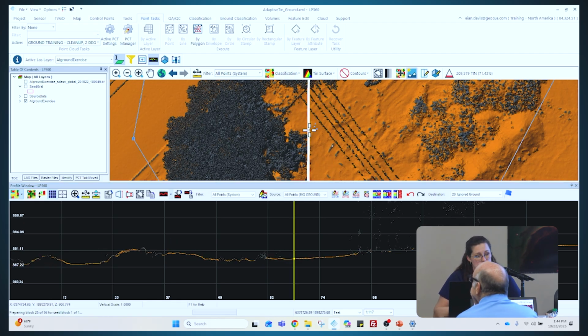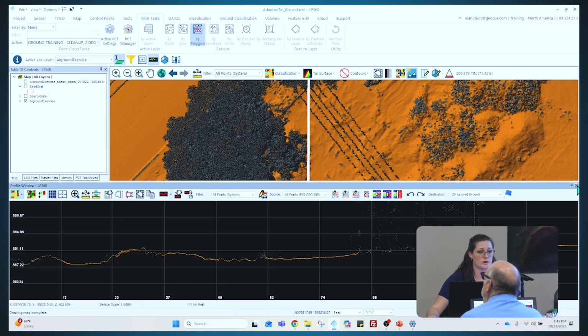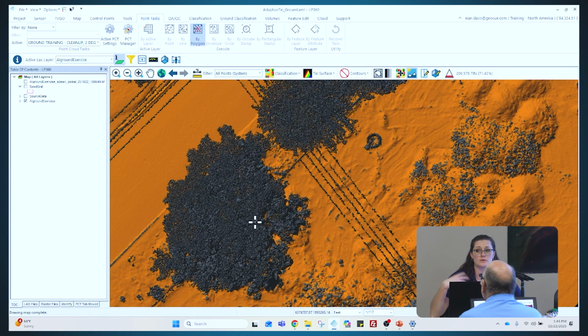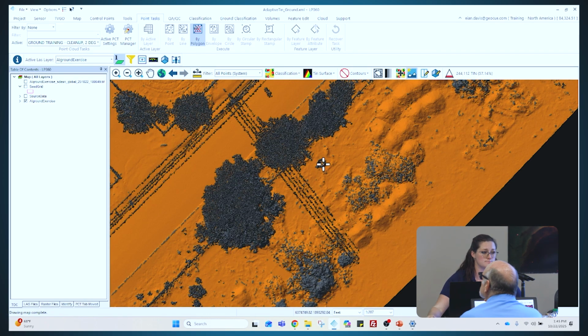It will then use all of the points that you have selected to classify any surrounding points within that given polygon. I have seen many users utilize this particular cleanup tool over the other just for forestry assessments or things of that nature to get more accurate contours underneath a thick canopy. It has also been seen in agriculture fields, like I said, ripraps, things of that nature that are going to have some kind of dynamic movement across your surface that can be a little more difficult to classify.